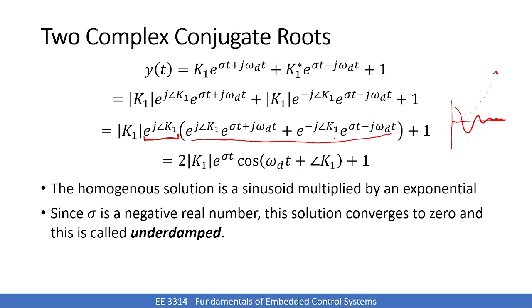Okay, so here we can see the response of our system is basically a decaying exponential times a sinusoid, which will look kind of like this, right? So if we have this 1 here, and let's say k is a negative number, that's how we get a type of response that looks like that, where we have a final value. The magnitude of this sinusoid is decaying over time.